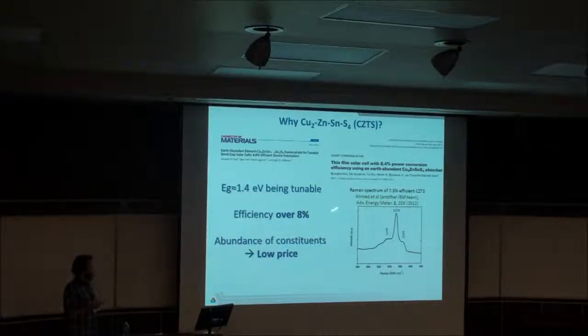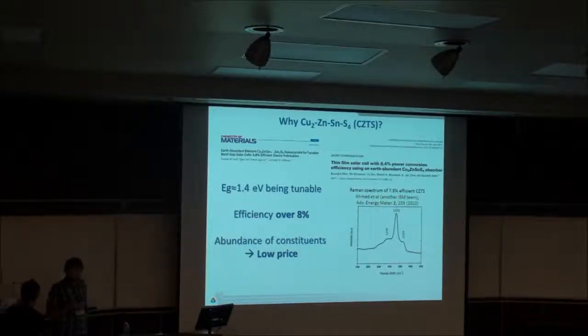Right now it's shown that the efficiency of these solar cells exceeds 8%, and there's still plenty of room for increasing it, because open circuit voltage is still below its maximum, and short circuit current is also still below approximately 33 milliamps per square centimeter.